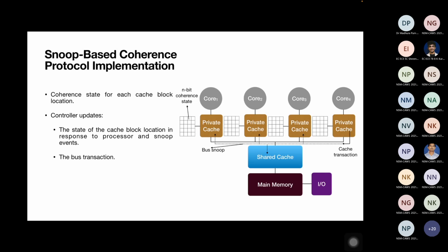You can see here I to S, there is a processor read transaction and there is a bus read transaction. The semantics of this is that from one state to another state, there is a state transition, and that happens when there is a processor-generated operation, which is processor read. And for that, there is a bus read transaction placed by the bus snooper. Here you can see this is basically core 1, which wants to read the data.